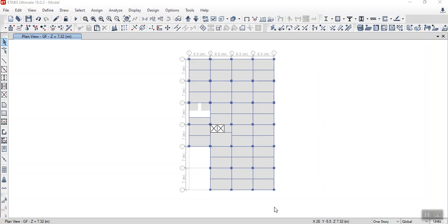Today we are going to design reinforced concrete slab in CSI SAFE. This video includes the process to export slab data to SAFE file from ETABS and import the slab data to CSI SAFE. Also, we will learn how to define load combination, materials, slab sections, and check short-term deflection as well as long-term deflection of slab in software itself. At last, we will design the slab as per Indian Standard Code.